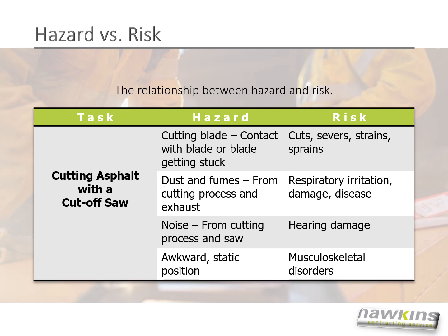Noise produced by the cutting process and the saw is another hazard. This hazard poses a risk of causing hearing damage. And the awkward and static position that the process places you in is a hazard that creates a risk of musculoskeletal disorders such as back pain.